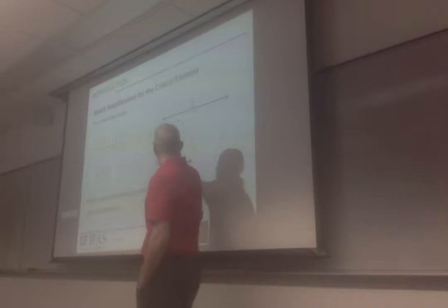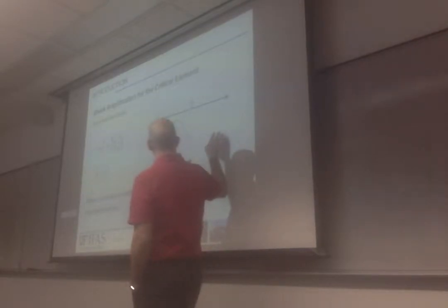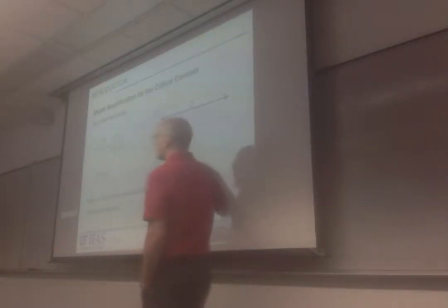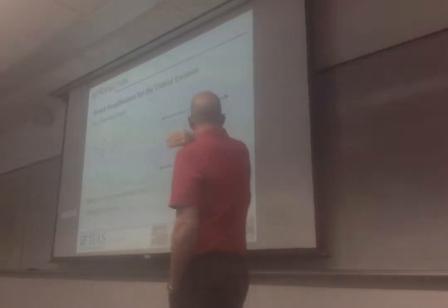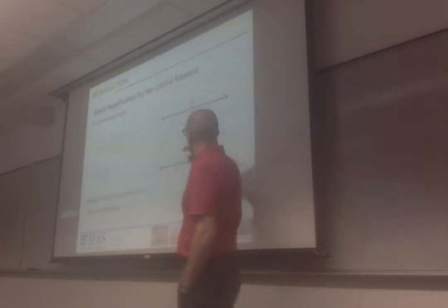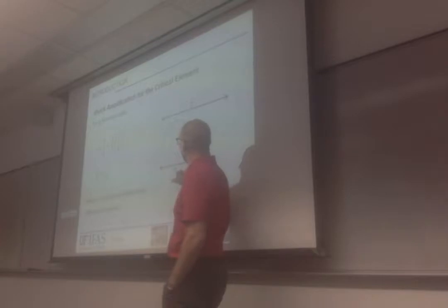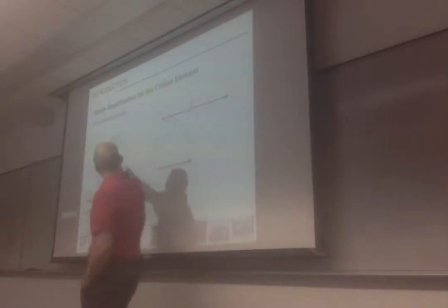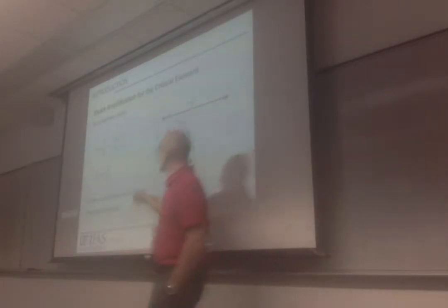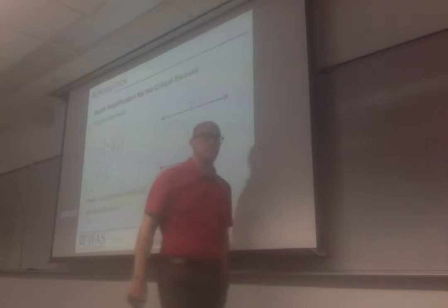So the duration is half the period. If you were to continue that half sine impact throughout a longer period, you identify that shock duration is half the period, and identifying that the period is 1 over the frequency, you end up with that equation to calculate the input frequency.